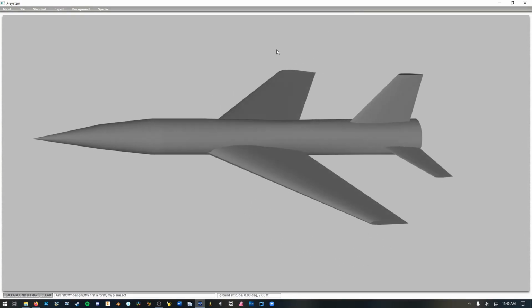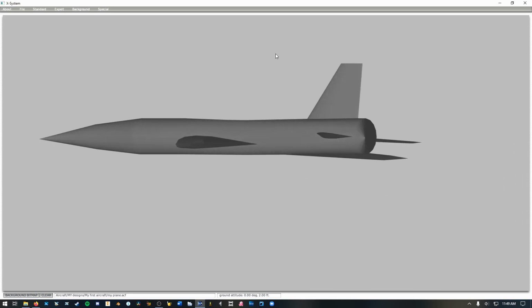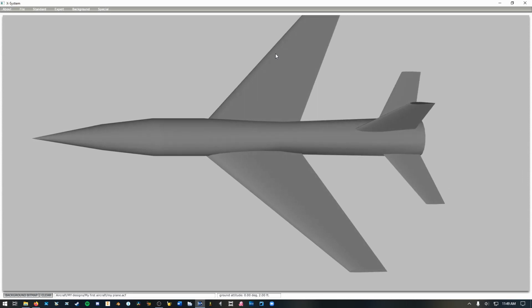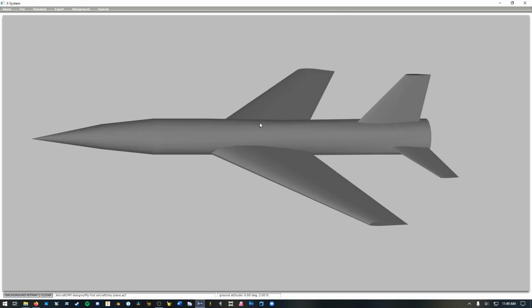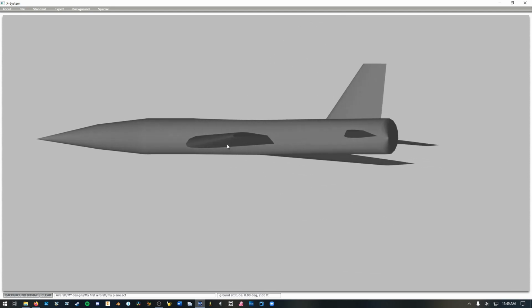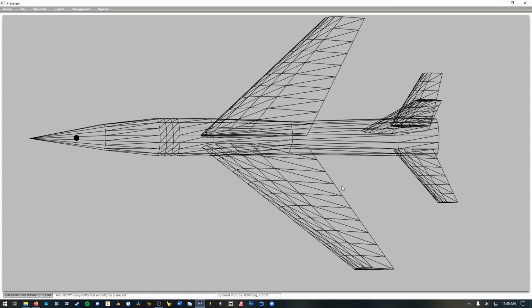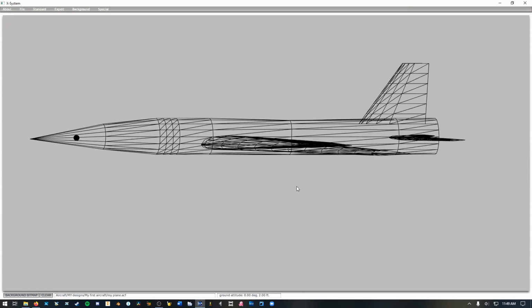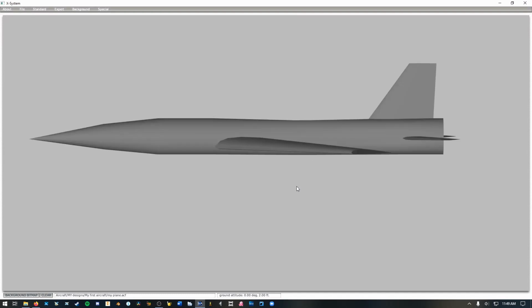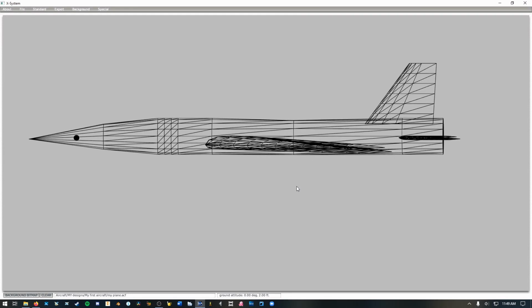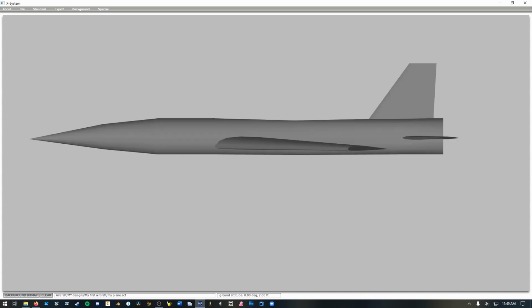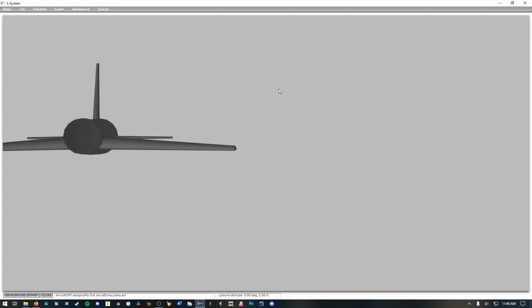And that's that. So the last thing you'll want to be aware of when you are creating wings, probably not when you're modifying them, is that you can change the airfoil that your wing uses. The airfoil is the shape of the cross-section of the wing. As you can see here, the elements are defined by these cross-sections. There is a program you can use to edit airfoils for X-Plane, although most of you don't have that. If you do, it's called Airfoil Maker. It's a bit tricky to use, but it's quite useful if you know what it does.